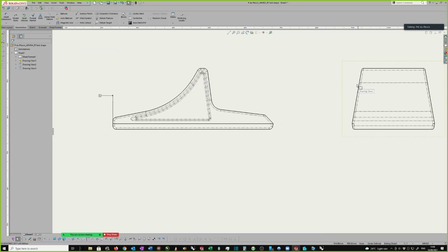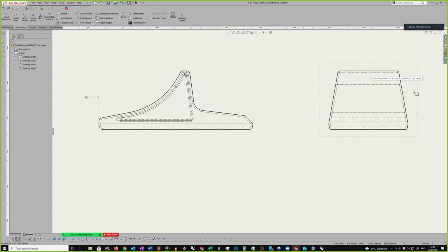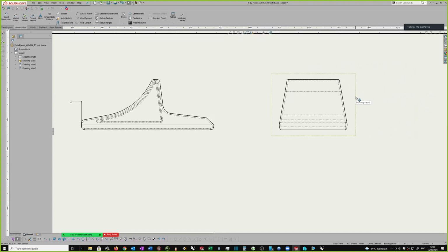But if I didn't have this view here, I wouldn't know that this part here is angled. You can see it's angled. So it's essential to put the views in just to remind you of what you did, and then also to make sure, well, whoever's looking at it can then see what's happened. So the question here is, how does one dimension what's happening on that face? I've got to come in at a right angle to this thing.